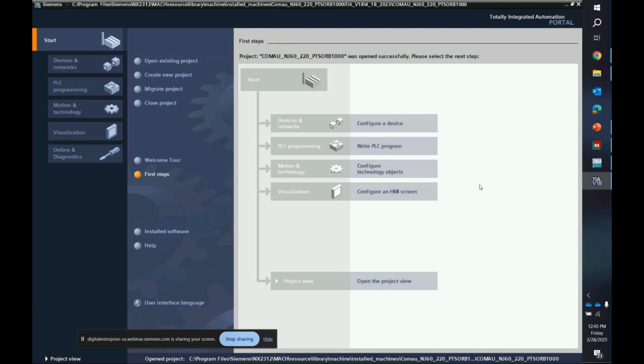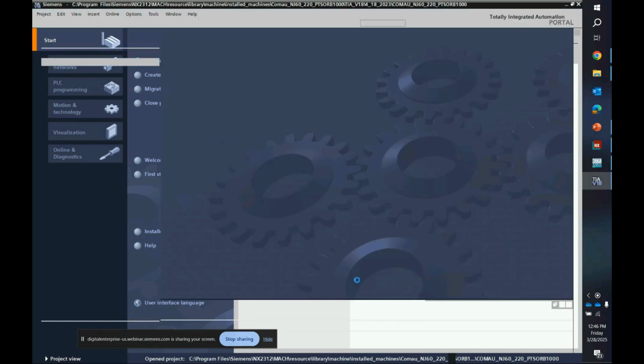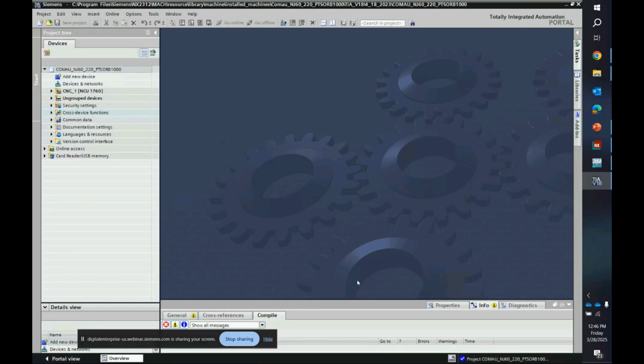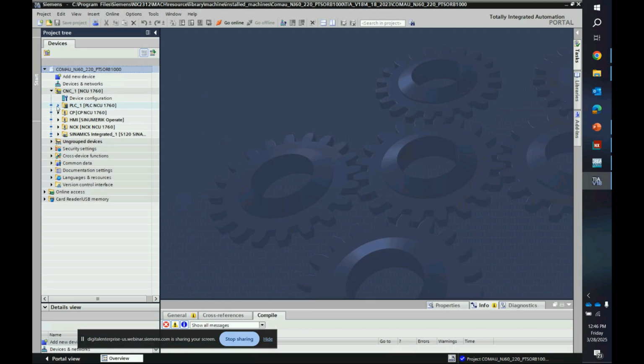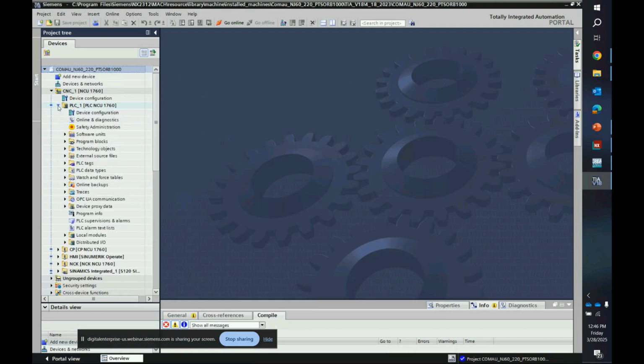So Siemens has a Run MyRobot portfolio, meaning there are 3, now 4 manufacturers, Comau, Stäubli, and Kawasaki, that are in a partnership with Siemens to integrate Sinumerik One controllers onto the system. Meaning from a commissioning perspective, all of the inverse kinematics, all of the calibration, all of the joint positions and linkages, all of that data has been pre-configured for a Sinumerik controller. So you can stand up, commission, put a Sinumerik CNC onto those 3 robots, all of their models, and have a very, very accurate CNC robot.